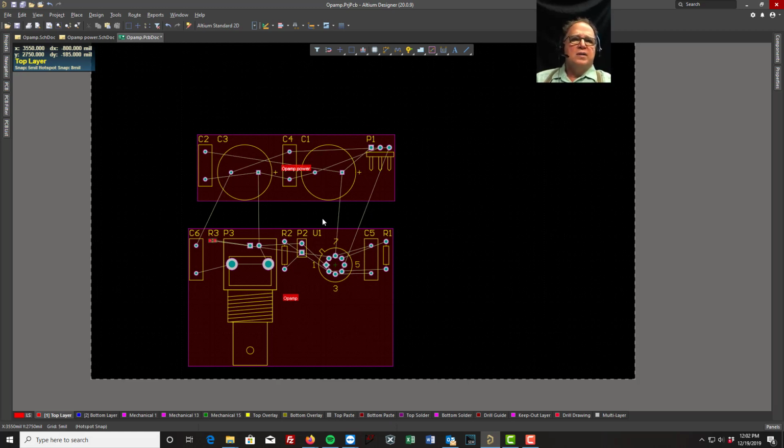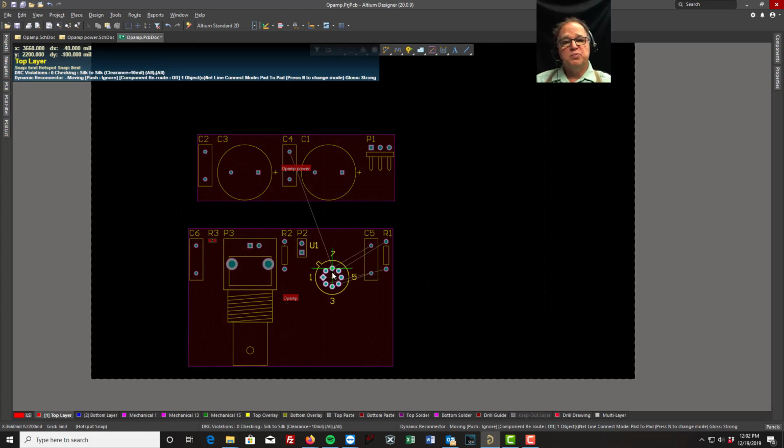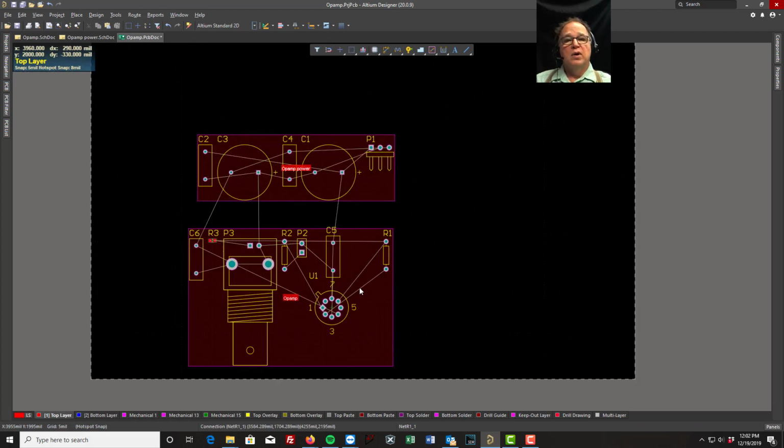When you do a design in Altium, you have the option to design that single channel and tell Altium to repeat it 16 times, 24 times, however many times you want it to. And when it does, and you move the parts to a PCB, it'll put each channel in a room. Now the advantage there is I can then come to the room and move these parts around inside the room and then tell it make all the other rooms look like this room, and it'll line them all up for me. That's where you have an advantage with rooms. Sometimes you can use it for a rule. I can set a certain rule inside of a room, but we're not doing that here.